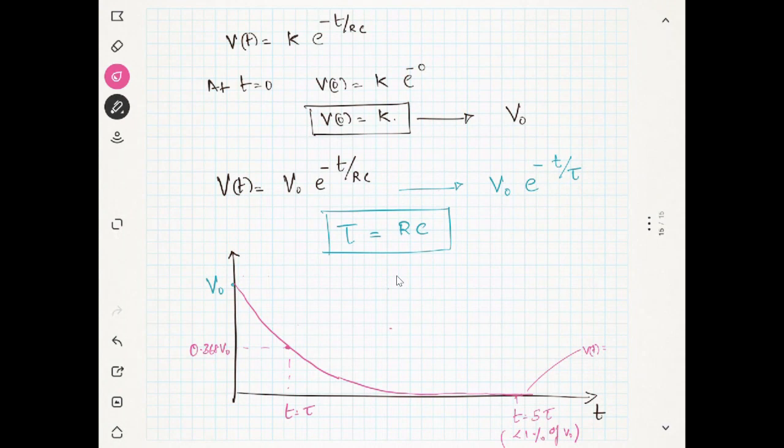Yeah, there are two different things. We are talking about a circuit without any source. Your capacitor is discharging. You understood? Your capacitor is discharging, which means the maximum is 100%. What is this? 36.8%. So if you are discharging, how much change is there? 63.2.